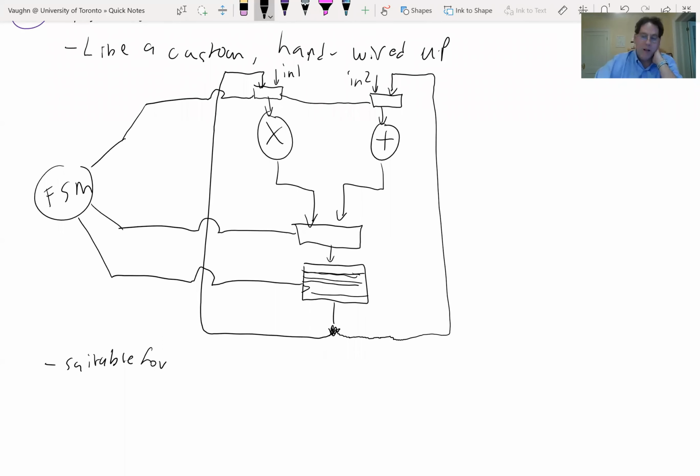Let's say we're doing Lab 1. In Lab 1, we're calculating a Taylor series expansion. So we actually don't want to do just one multiply add. For every computation, we have to do about 6 multiplies and additions. So when does this make sense instead of doing it streaming hardware? Streaming hardware, I would just make 6 multipliers, 6 adders, and it would compute everything I need spatially. This is not computing it spatially. It's computing it more sequentially. So when should I use this?